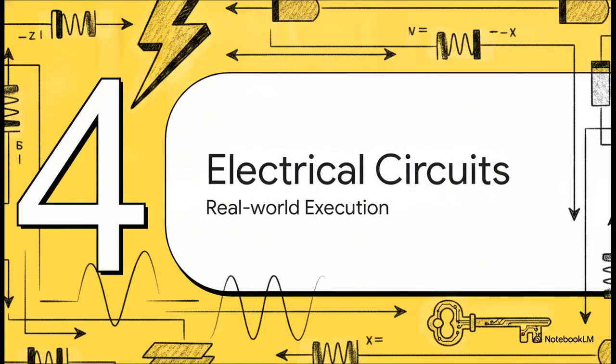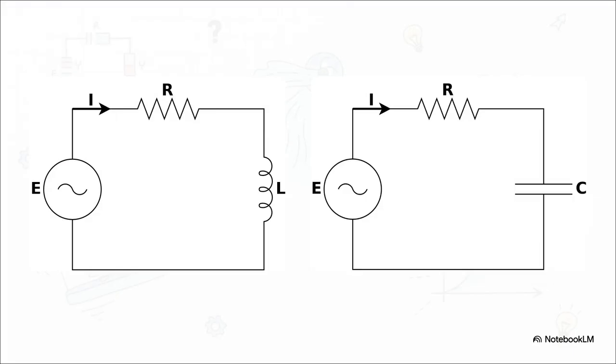Section 4. Real-world execution, electrical circuits. Let's see how this actually operates in the physical world. Think about standard series RL and RC circuits. These are first-order circuits, meaning they only include one energy storage element. When we sit down to analyze their dynamics, like, say, tracking the current right after closing a switch, the mathematical result naturally forms a first-order linear ordinary differential equation.